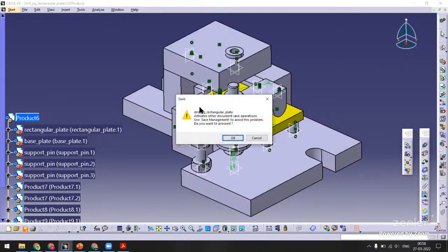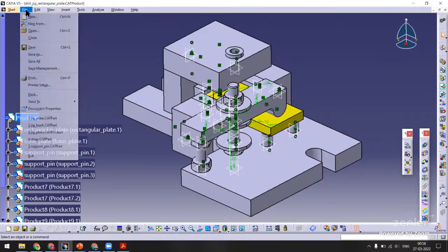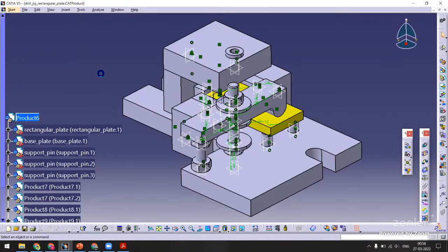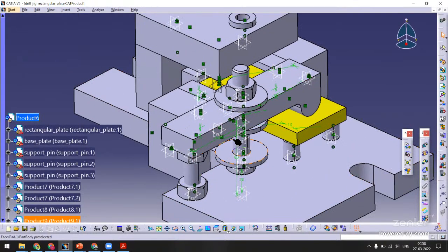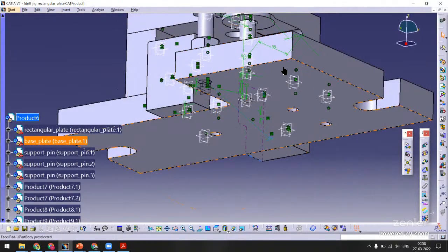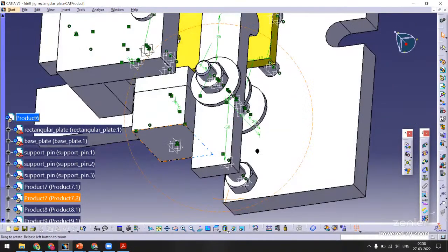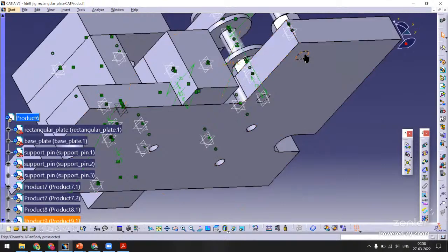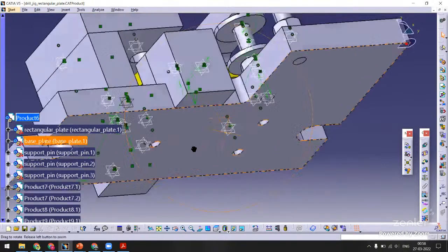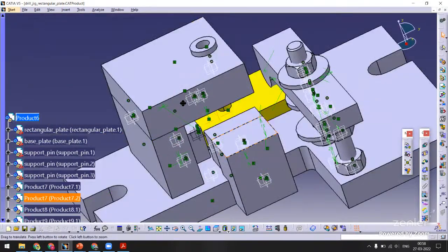So now what are the pending items in completing the drill jig detailed design, that is the 3D design. So we need to apply the spring, and then it is also very important that we can apply some feet for this drill jig. It will be good. Maybe we'll have to adjust the length of the screws, and then we'll have to make all the holes for fastening these plates.